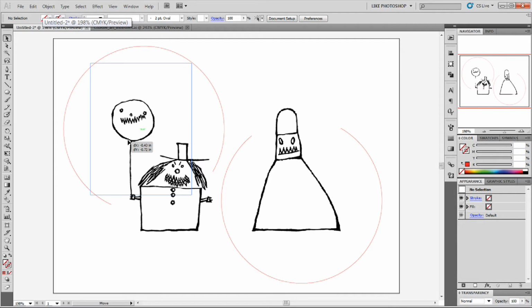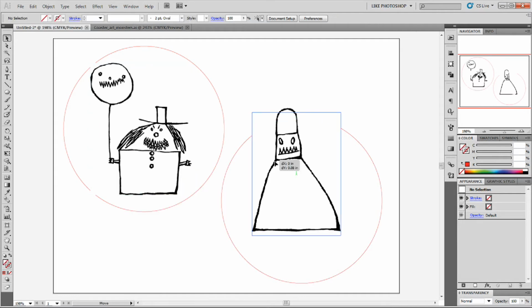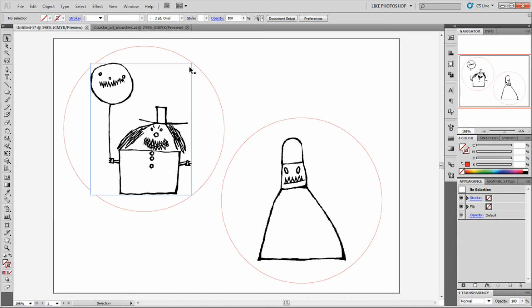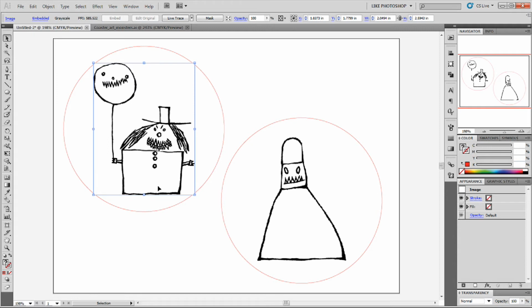And the black color will tell the laser etcher or the laser cutter that it actually just needs to etch and not cut. Now, one thing to keep in mind is a cut needs to be a true vector line. So it's a continuous line of a path, and etching can be either a vector line, curved or straight, however it's designed, or it can be an image, like I call it a raster image, that's a series of dots. But a cut actually has to be a vector.